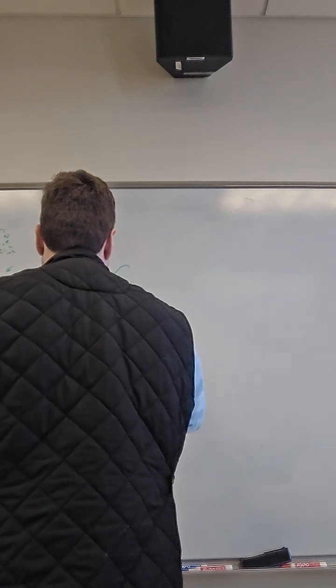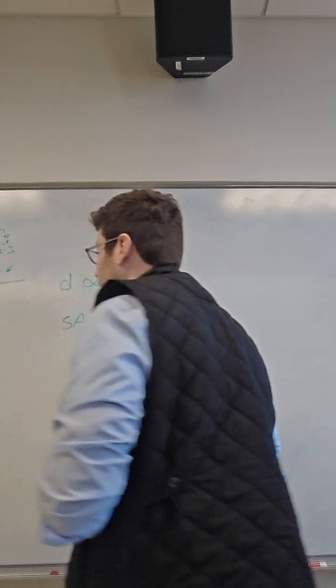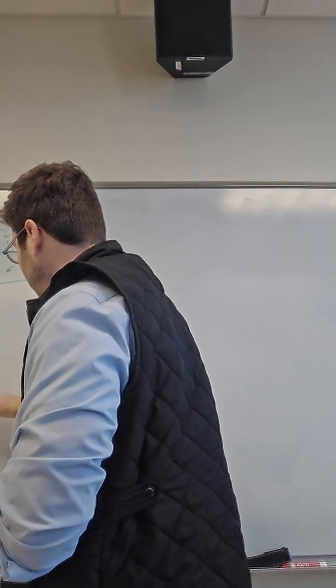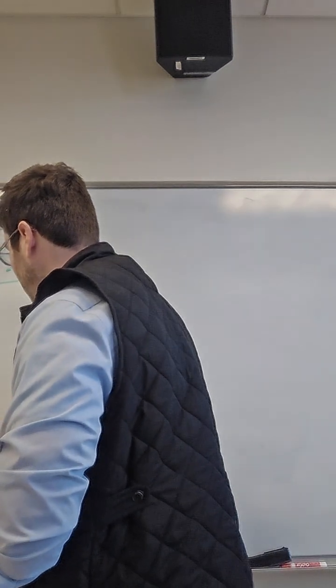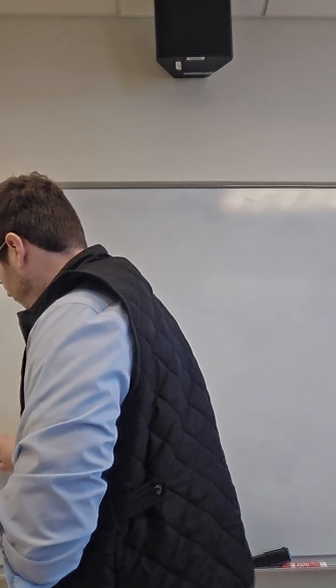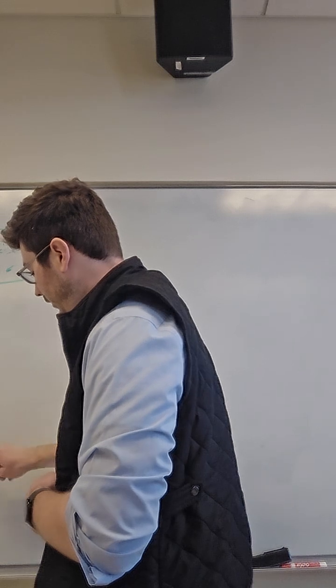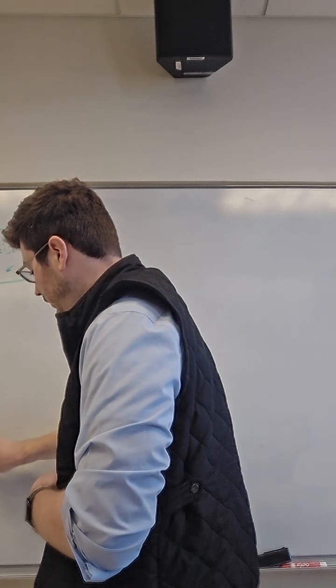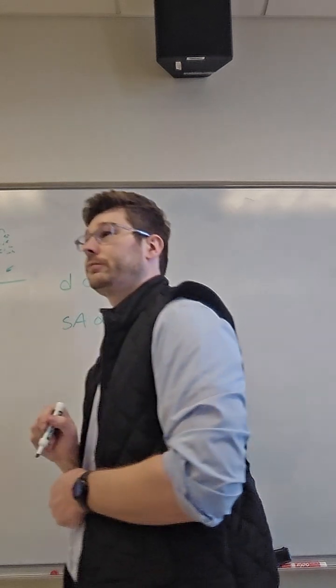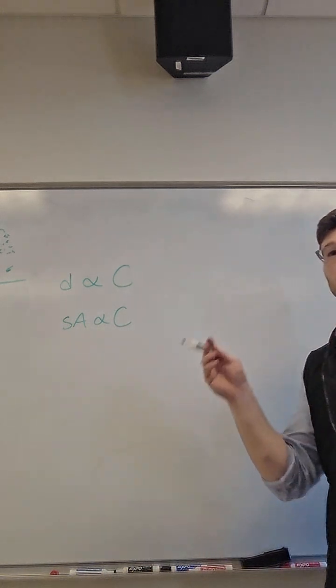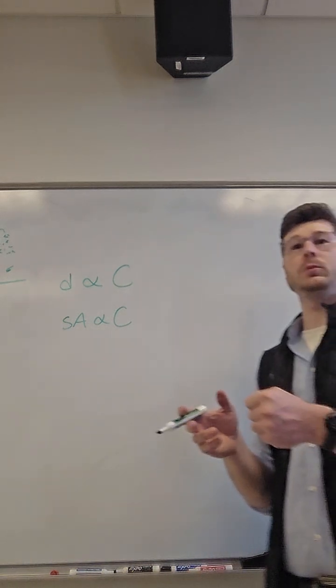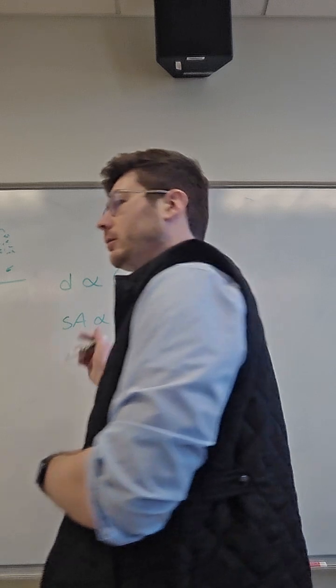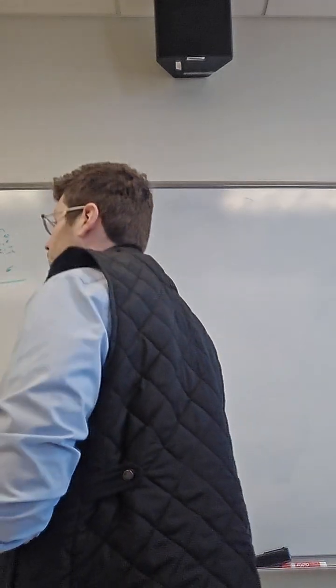The other thing is pretty much what I just said, which is surface area. So surface area is also linked with capacitance. If we had really big plates, this is literally a small capacitor versus tiny wires and very large plates. This would be a much better capacitor, assuming the distance is the same between the 2 plates, than this one. More plates means more electrons can fit onto those plates within that capacitor, higher capacitance.